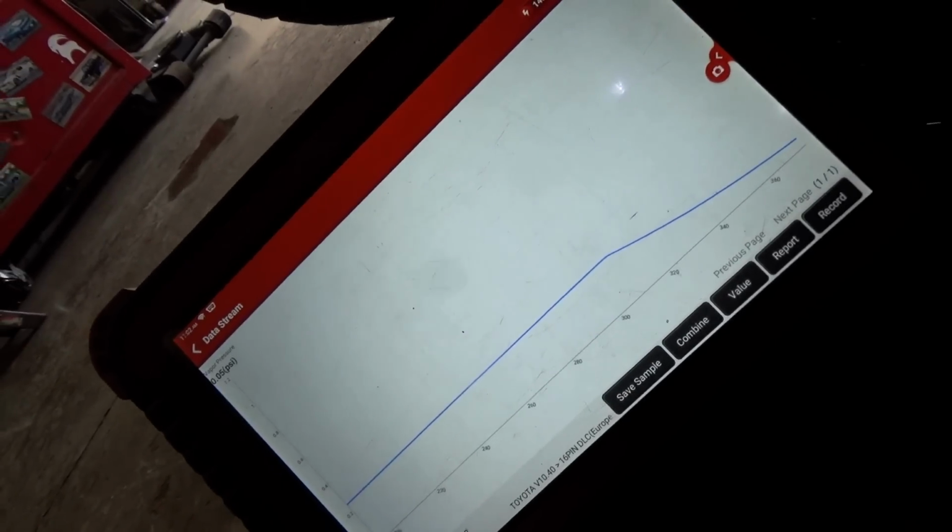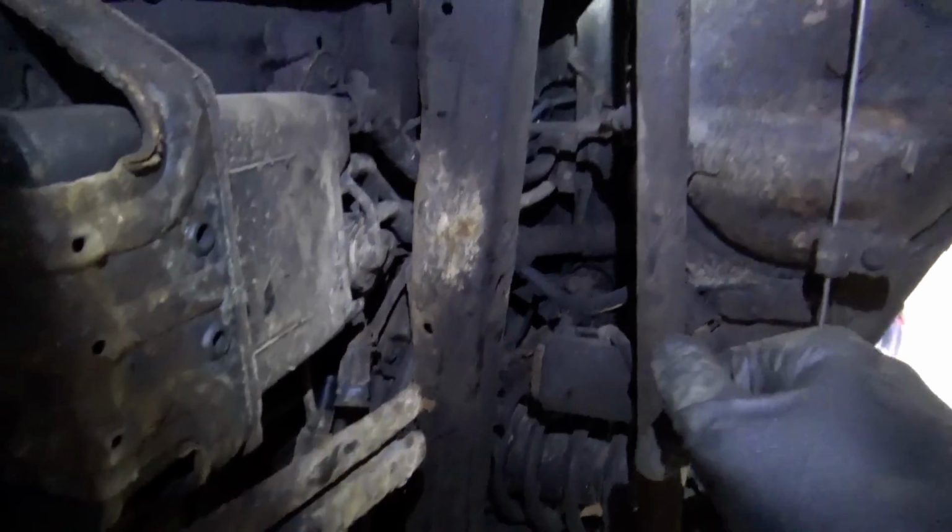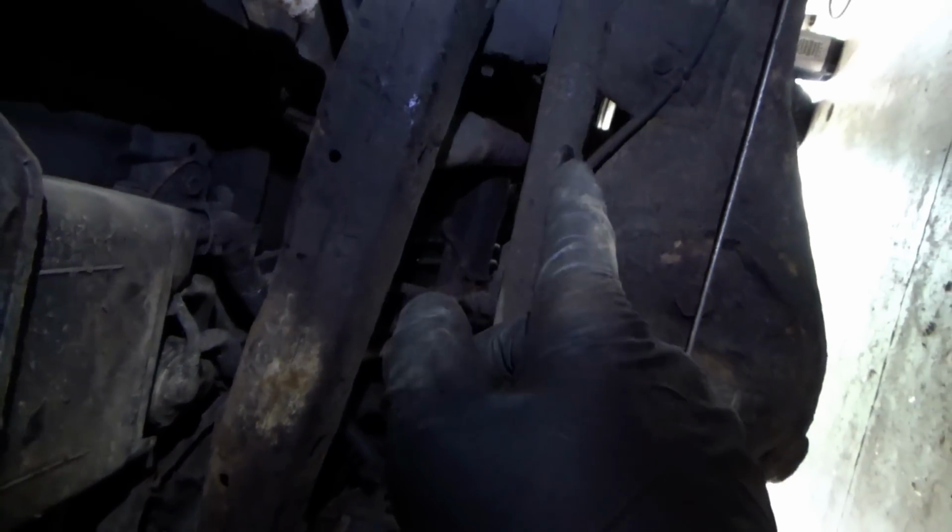Simply beautiful. Okay, so this EVAP system is fixed once we install the new bypass solenoid, and the customer will have to take care of his exhaust tailpipe. I'm guessing just replace the tailpipe, but the flange is rotted off, so he'll deal with that later.